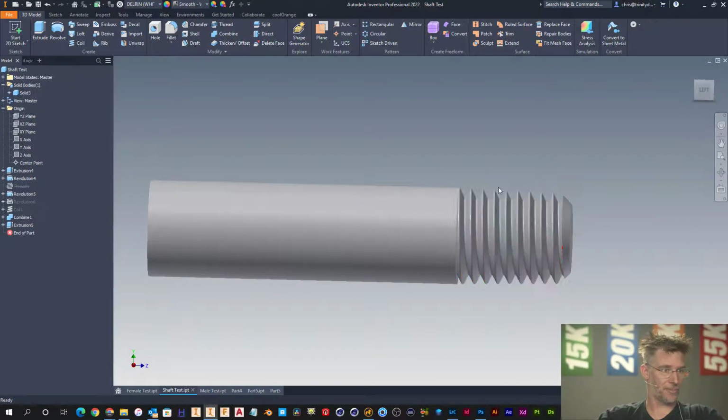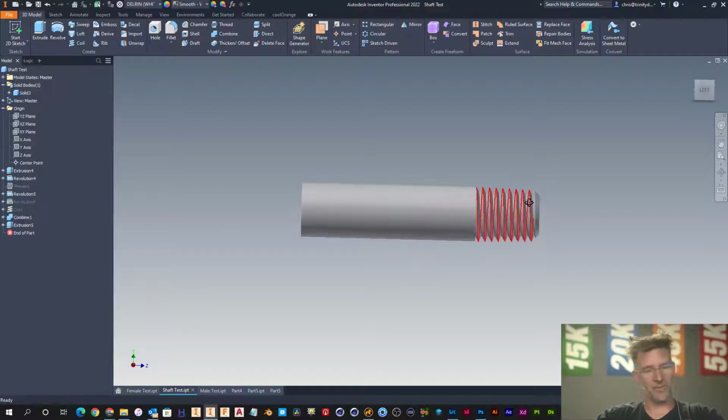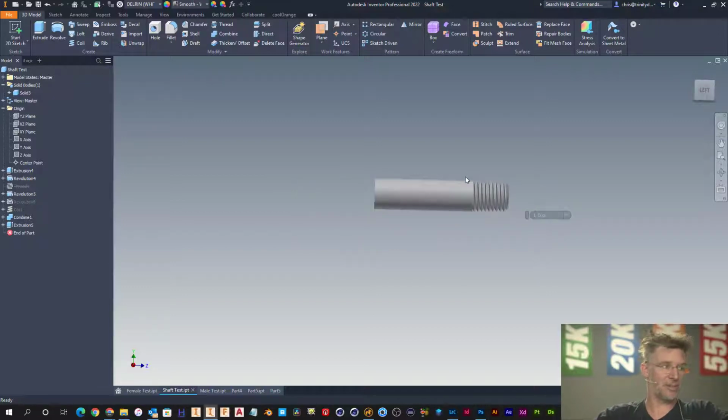So there you go. And believe it or not, when we do run these models and our customers see this stuff, they can tell whether that's tapered or straight. That's why I kind of like to do the threads in Inventor and then export that stuff to Modo. The problem I run into there is I don't have quad polys on the Modo side, so when I'm trying to do like a bent piece of pipe that's got an NPT on there, it's super hard to get those UVs unless the bent tubing part was created in Modo itself.